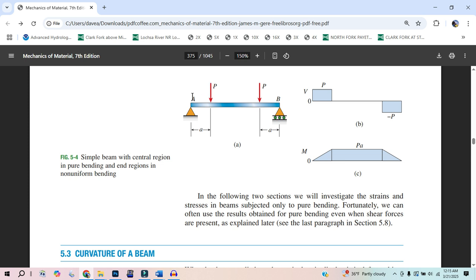But we're just worried about the shear. So we have an upward force and a downward force equal to P. And if we take that little chunk, those forces are causing a rotation in this clockwise direction. You just have to get used to saying that's going to be a positive shear. The other way to look at it, so let's take a look at that little chunk, is that I would slice it up, because that positive shear is going to happen from here to there. See how this line is always positive shear?